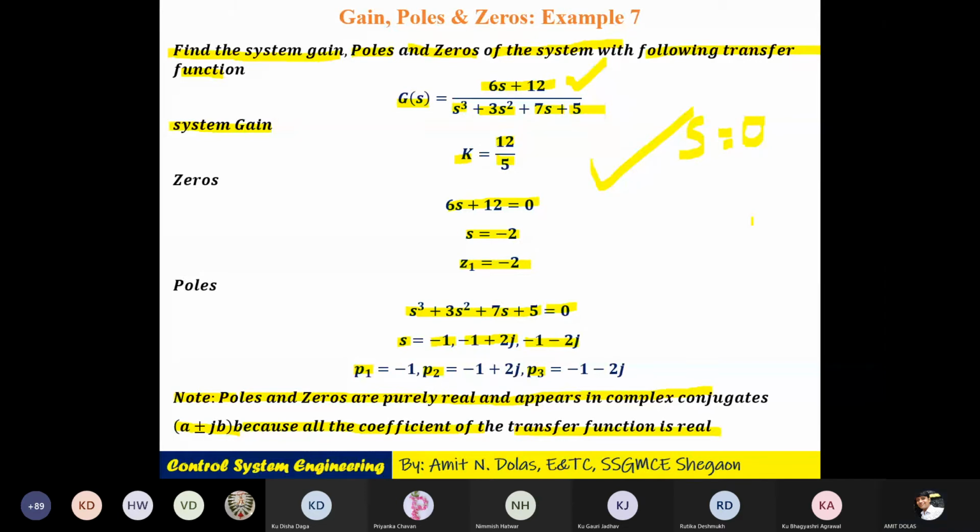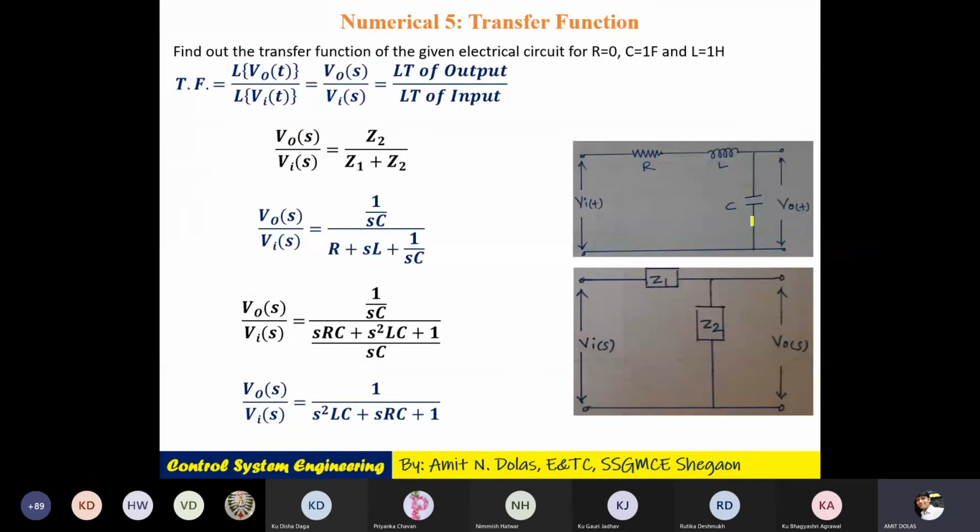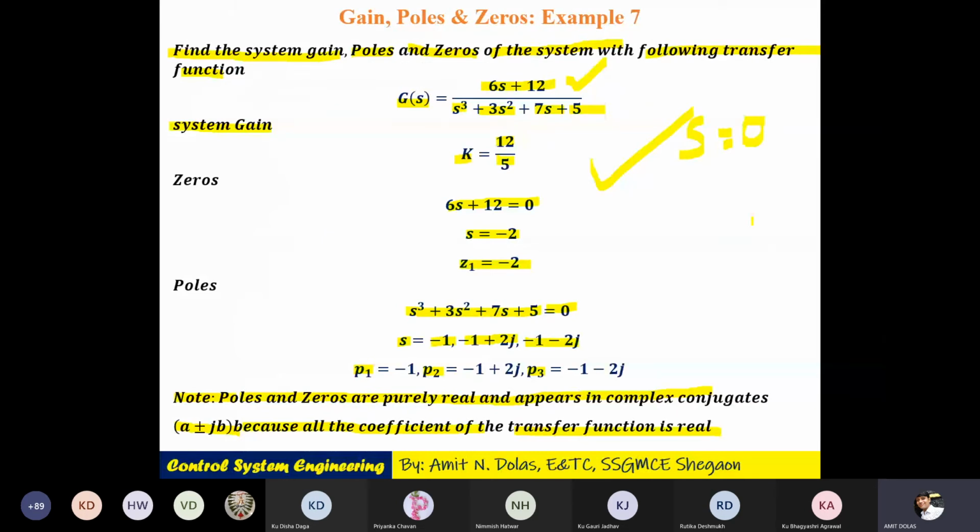With the condition insignificant pole divided by significant pole greater than or equal to 4, we can neglect insignificant poles, and we may calculate the equivalent of any given complex transfer function. Now up to this we have seen all regarding the transfer function.